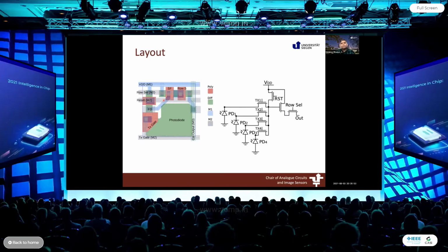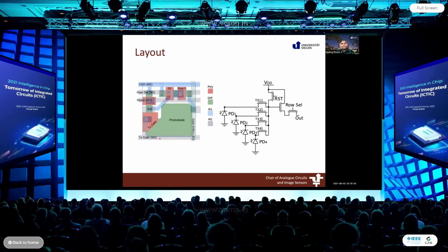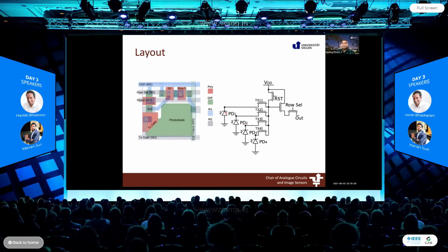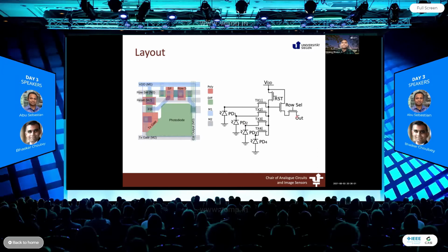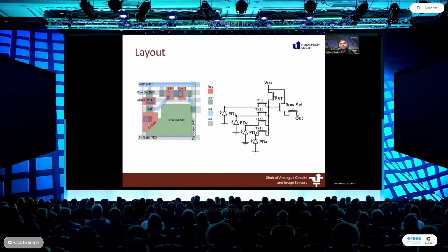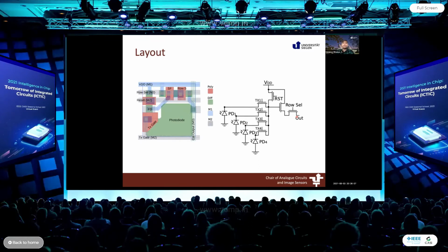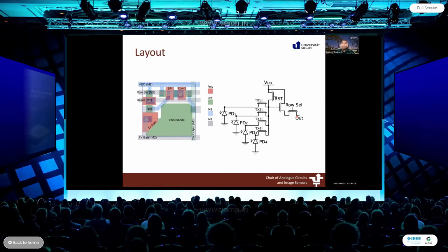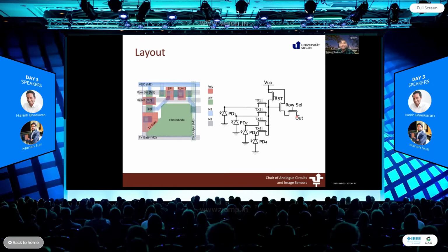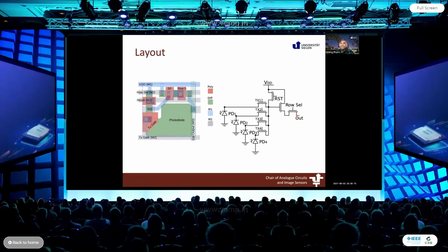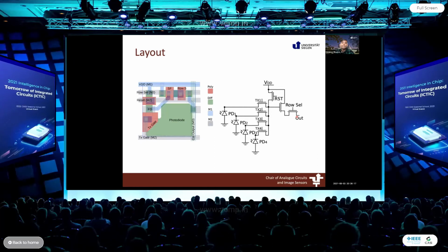So people have gone through multiple ways to increase the diode area. We have shared the neighboring transistors, with 4 photodiodes sharing the readout electronics, and that way increased the diode area. So all these techniques have been tried. But this does not lead to a large number of transistors in the pixel, or a large number of memristors in the pixel, to actually do any neural processing.